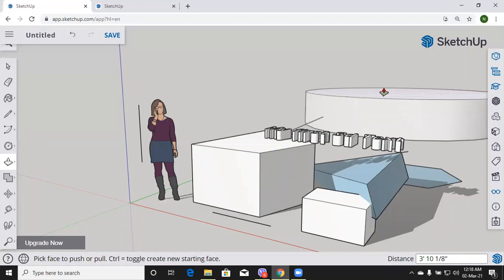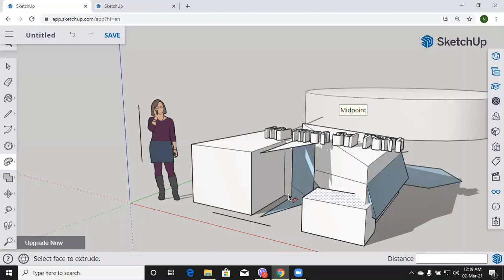And then next is Follow Me, used to define 3D contours, selecting a 2D base as the section and a 2D path to follow as direction. So you can use even this Follow Me also here. Okay, so this is a curved face. In this, extrusion cannot be used over here. So now here you can follow this. Like this, you can make any shapes.